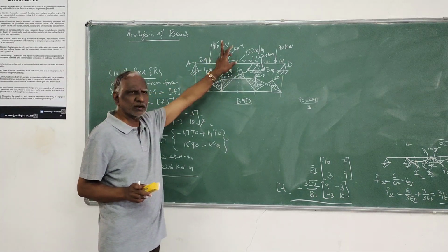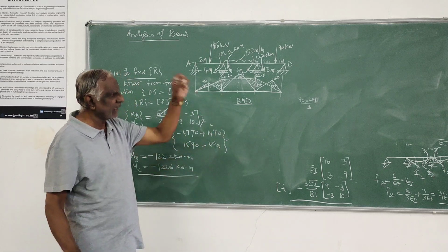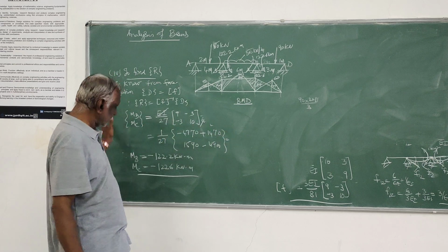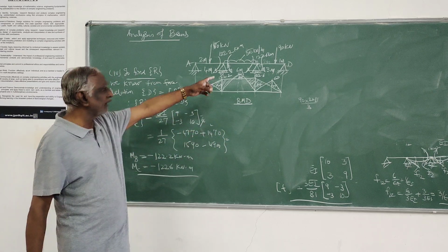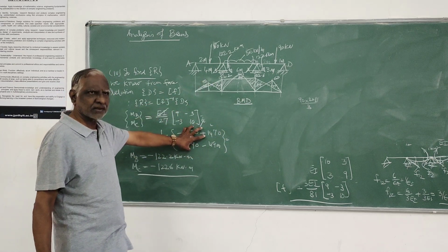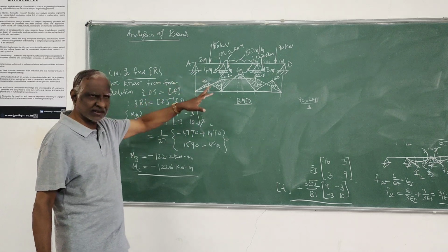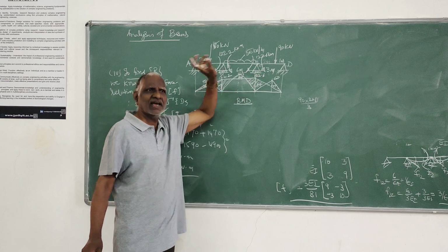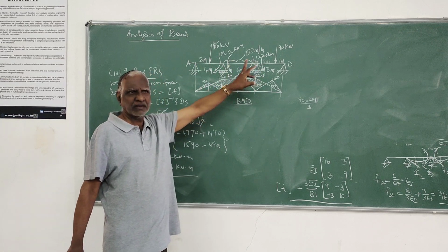Then indicate the coordinate direction as sagging. Then remember those standard case formulas, show the diagram and evaluate the DL matrix. Then the DR matrix, normally it will be 0. If it is given, then you cannot select the support moment as the redundant.